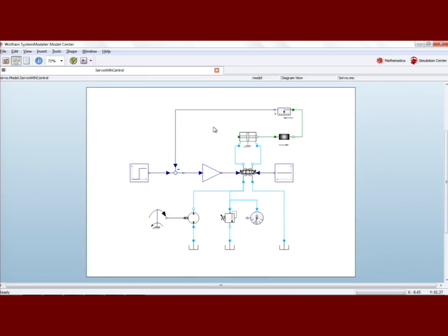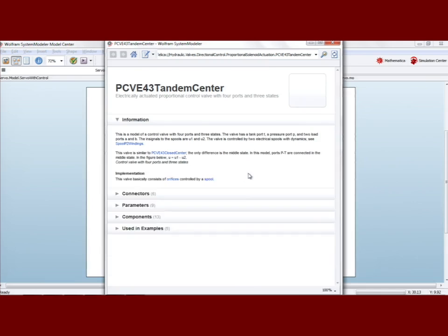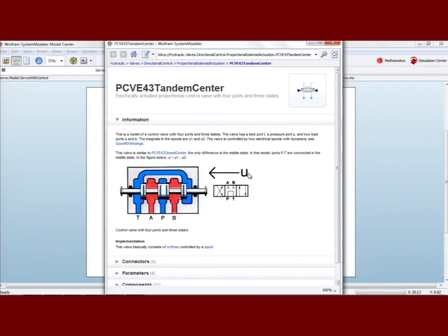In order to accomplish this, we have a hydraulic system. We have 3 tanks. Look at them here. And we have, for instance, a motor here. The motor will build up a pressure, and depending on this pressure, we will then be able to move the cylinder back and forth. Of course, that depends on how the valve is actuated. So let's look at the help here. How do different components work?